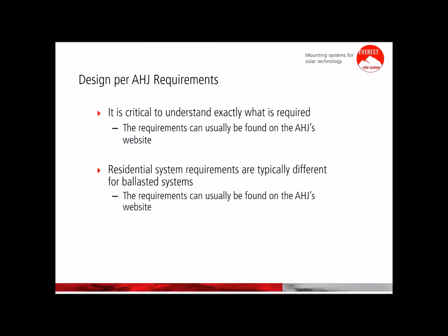The first thing that is, I would say, critically important for designing any ballasted system is really understanding exactly what the requirements are for the AHJ. This can vary, at least in California, pretty dramatically from city to city.